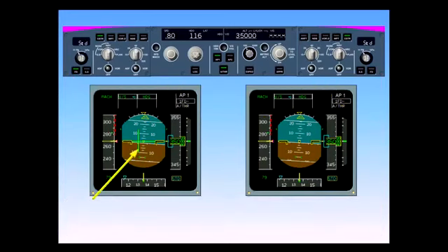Also note that when the Flight Director was re-engaged, it came up in the basic vertical speed and heading modes. Whenever both Flight Directors and the autopilots have all been disconnected and one is switched back on, it reverts to its basic mode.